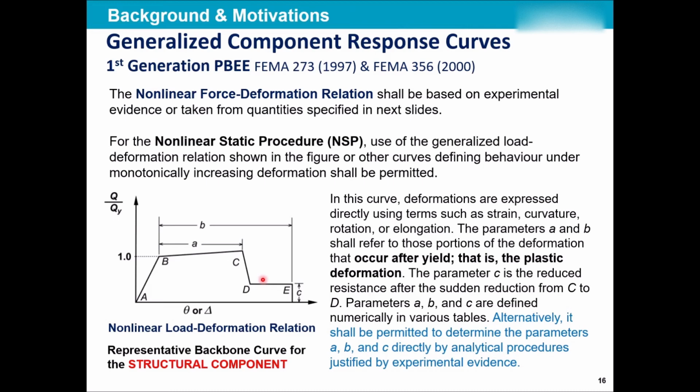Now, if I have the behavior curve for that single column, it can be applicable to all other columns that my structure has as well. So if I can get the performance of that column under, let's say, force, displacement, or moment, rotation, I can expand this to a general structural behavior.